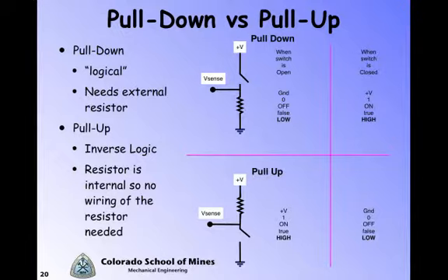If that switch were closed, however, then current's going to flow from the voltage source to ground, past V-sense and through the resistor. In that case, you can see that the voltage drop will occur across the resistor, and therefore V-sense would measure a plus V, or typically a 5-volt voltage signal. And in that case, we would say the value was 1, or on, or true, and in Arduino speak, high.